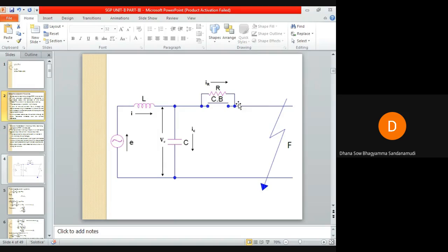You just connect a resistor across the sphere gap. You have already seen in the case of lightning arresters how the sphere gap will look. Simply, it is across the contact gap. That's all, nothing else. The analysis of resistance switching can be made to find out the critical value of the shunt resistance, so we can determine what the value of this resistor should be.